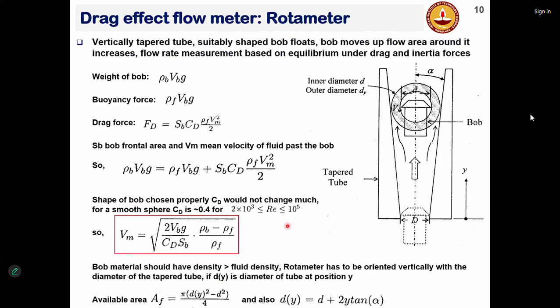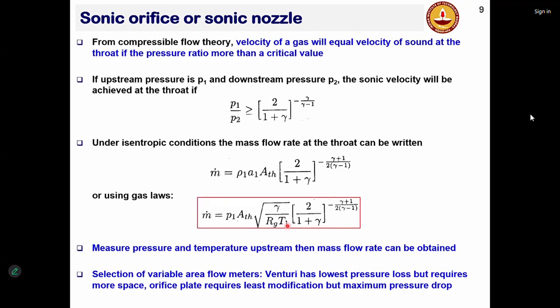So there is also a concept now, like if the velocity of a compressible fluid goes beyond a critical value, then the nozzle acts like a diffuser and the diffuser acts like a nozzle, something like that. So we are not talking about the supersonic case, sorry, the hypersonic case. We are only talking about the supersonic case. That typically happens at which conditions? I just forgot it. It was hypersonic, you talk about very high Mach number, typically close to Mach number 10 or above that.